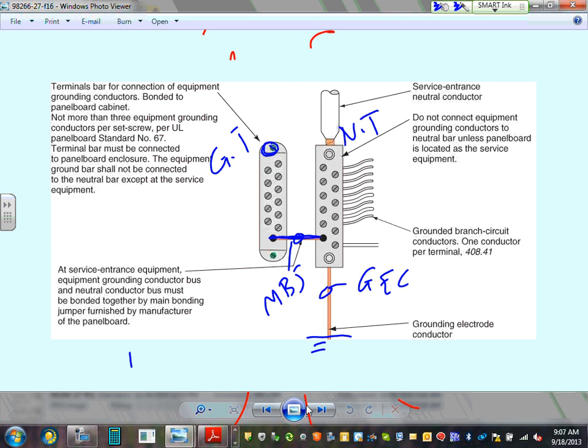And of course, right ahead of it, what you're going to need is a circuit breaker, like a 200 amp circuit breaker. That will be landing on two of them, one on every side. Any comments, any questions, guys? You can put all your neutral conductors in one bar, and all your equipment grounding conductors no more than three of them under one screw for the equipment ground conductor. These have to be a screw.